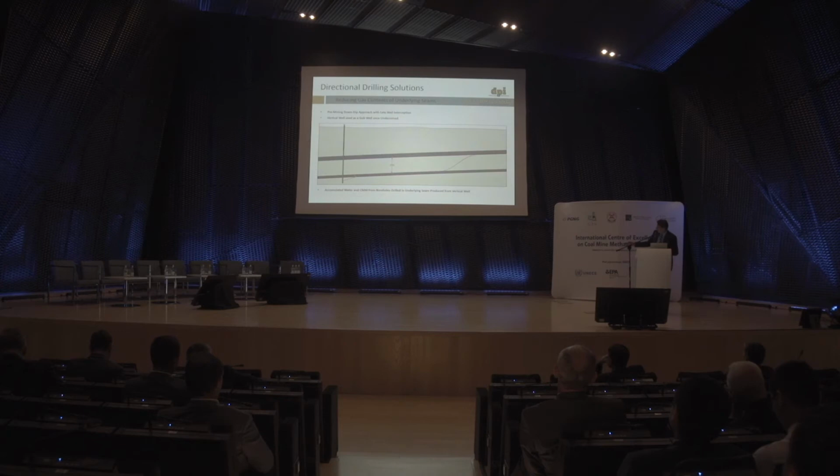But the other point is this vertical well could be drilled from the mining level to this point, and the gas could be collected underground and not have to go up to the surface. So what we would do is we would drill a short vertical component, and all of the water that usually impedes gas flow in these underlying boreholes would drain there, and the gas would be produced from the vertical section.